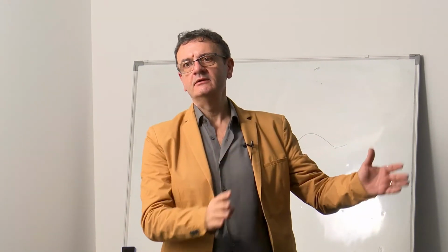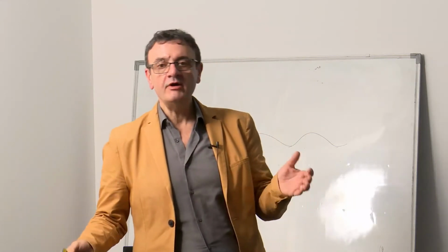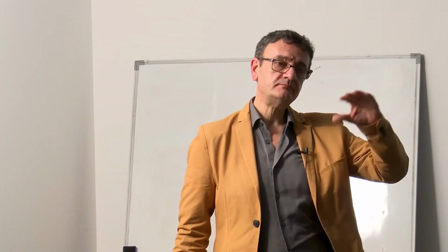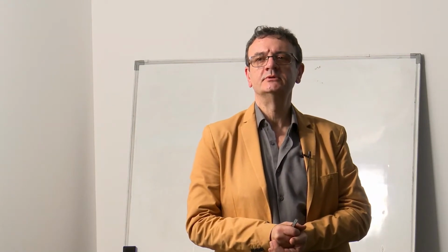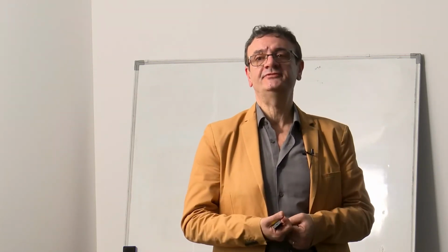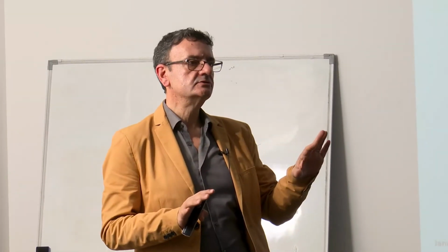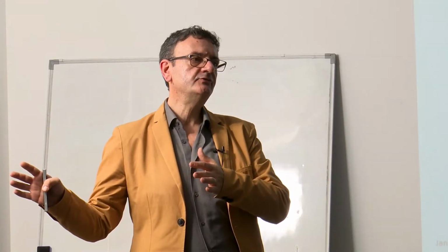Yes and no. You can claim that when you're talking to a layman, because you can say I have 100 decibels, my wall is 40 decibels, so on the other side is going to be 60 decibels. However, remember that sound is made up of various frequencies. What is the amplitude envelope of that spectrum? Is the intensity higher at low frequencies or at high frequencies? That makes a lot of difference. So how do we get to know that? You can't. So don't get into that. Just claim the obvious: you have 100 decibels, the other side is going to give you 60 decibels if the partition is 40 decibels. That's it.